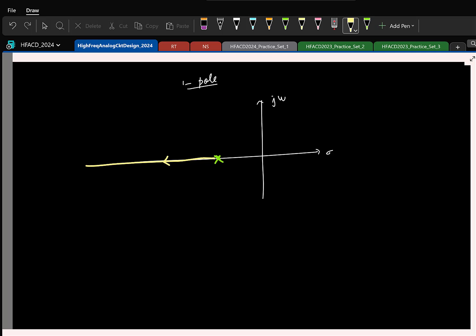So now you see the closed loop poles for a first order system, where is it lying? Yeah, the real axis, but with respect to stability, it's definitely in the left half of the S plane. So for any value of DC gain you choose, the first order system in closed loop is definitely stable. This is again another way of observing the same thing. Cool.